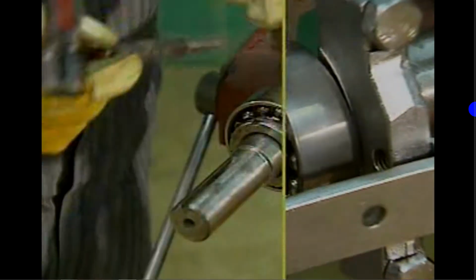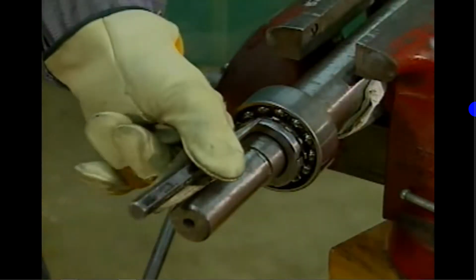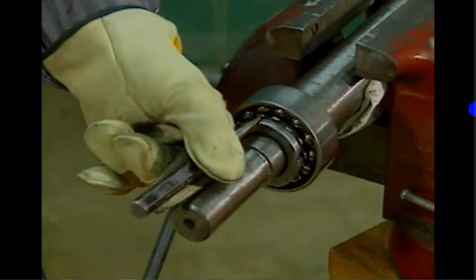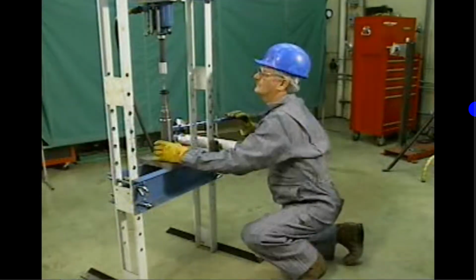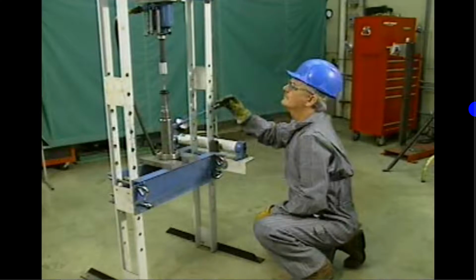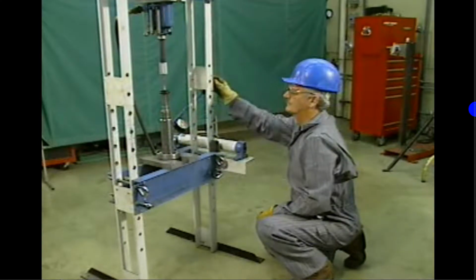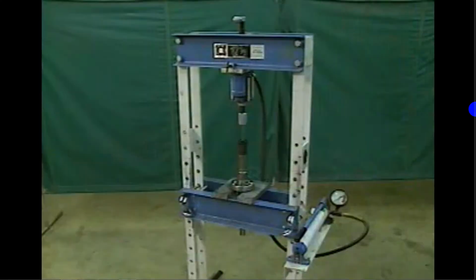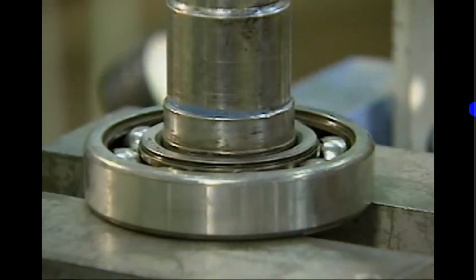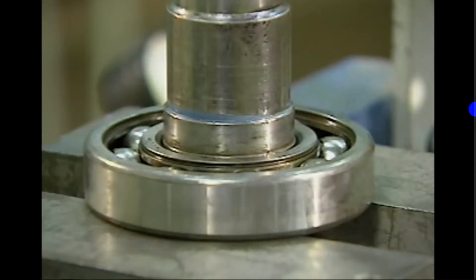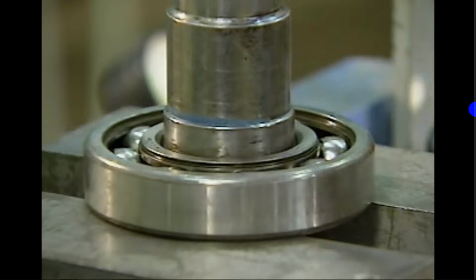In this part, we'll look at two methods for removing the press fit inner ring of a bearing from a shaft. The first method is used when the shaft can be removed from the machine. This method uses a device called a hydraulic press. A hydraulic press is a machine that is frequently used to apply pressure to the parts of a piece of equipment that is being assembled or disassembled. A hydraulic press removes a bearing from a shaft by holding the bearing in place and pushing the shaft through the bearing.